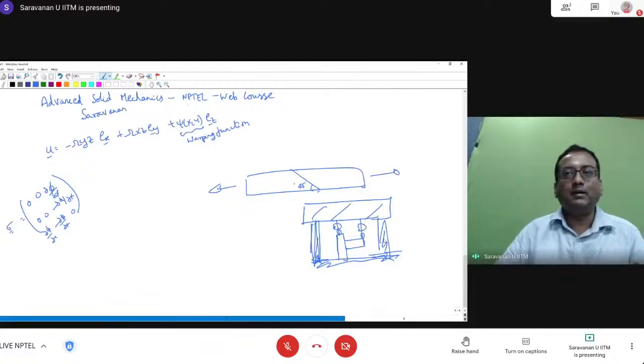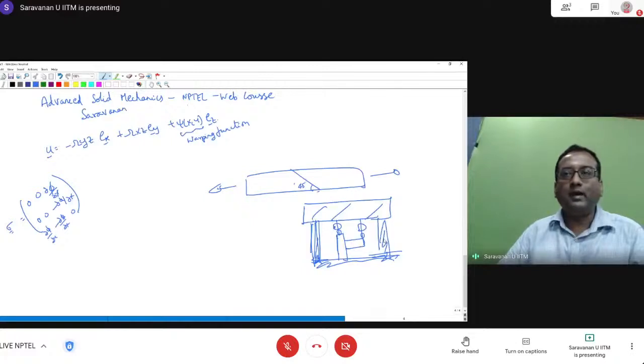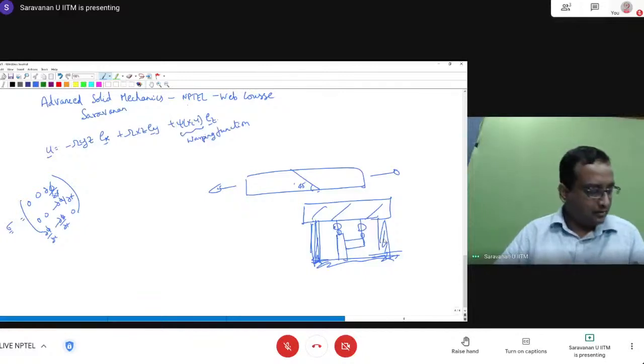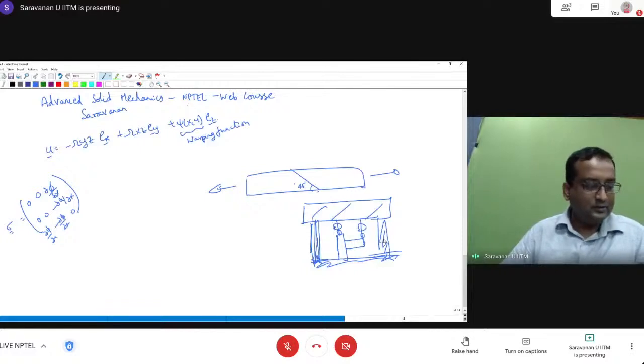But plane sections remain plane is an assumption where you get through even if the metal is inhomogeneous, deforming plastically, deforming viscoelastically, and so on. And it has been experimentally verified that plane sections do remain plane. So that is an assumption that you make which is universal, but other assumptions are to be satisfied. Any other questions?